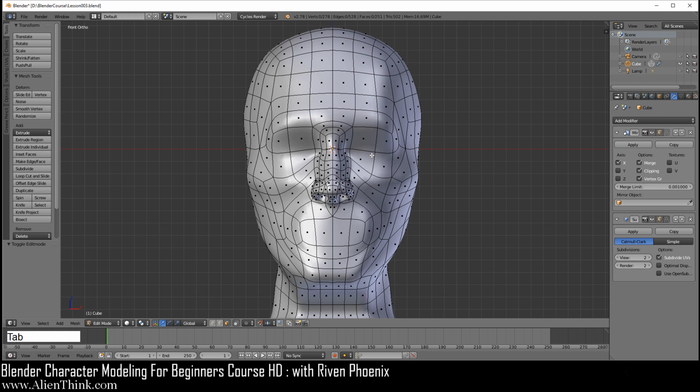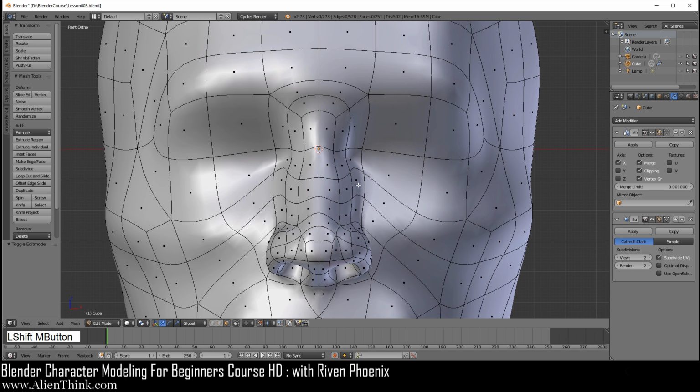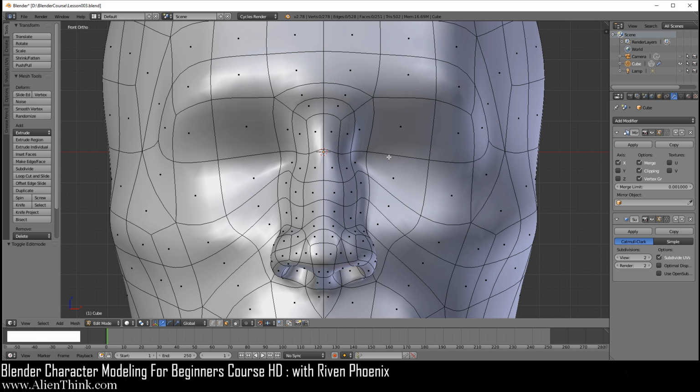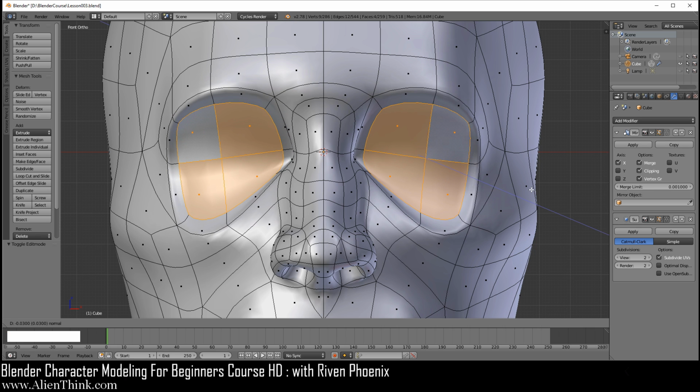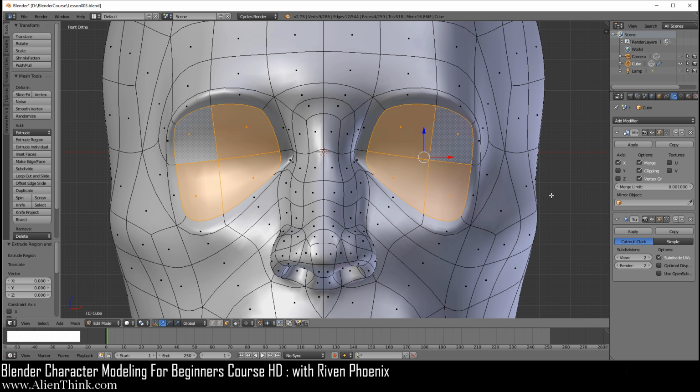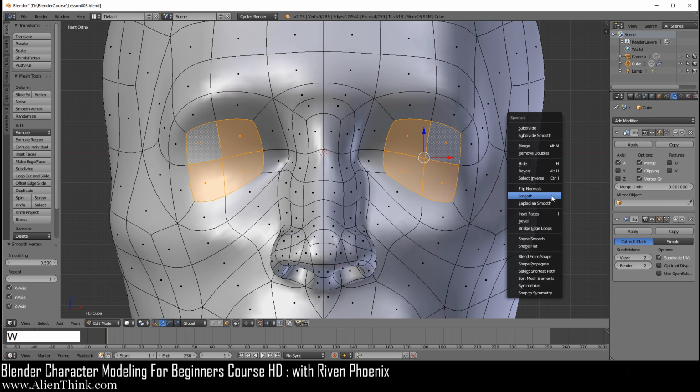So now we're going to define the eye. Now go ahead and click on Tab View and zoom in like this, do Shift and middle mouse button to just get it just like this over here. What we want to do is go ahead and select on this, Shift key down, select these guys. I'm going to press E to extrude, right click to cancel this. I'm going to smooth it 4 times. W, 1, 2, 3, and then 4.